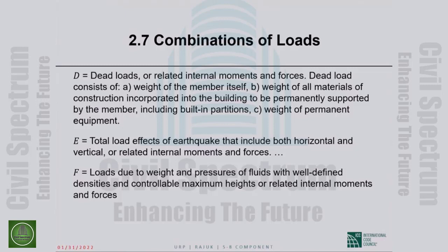I will go into those details in probably the second earthquake segment. Okay, so that I will refrain from discussing today, but for now, two things. One I just said, another I did not say. E is a strength level force. So in strength design load combinations, the load factor on E is 1.0.